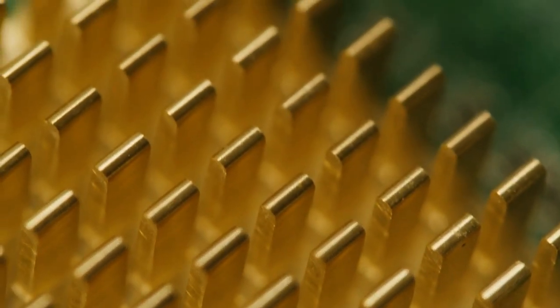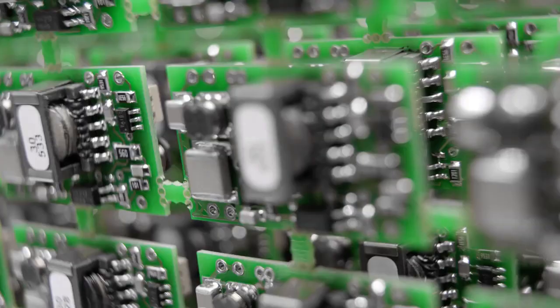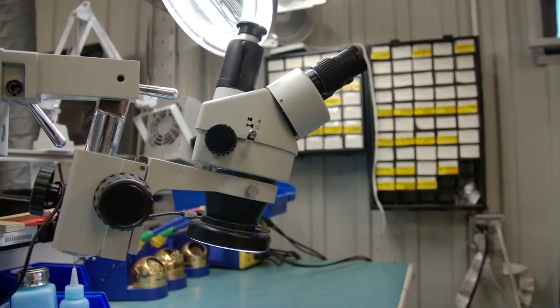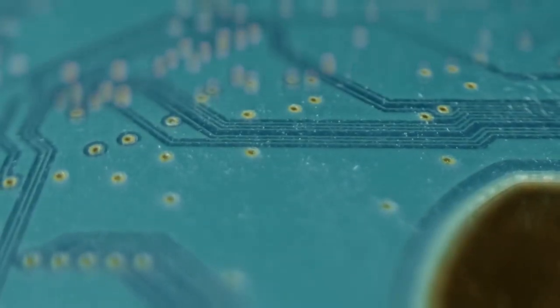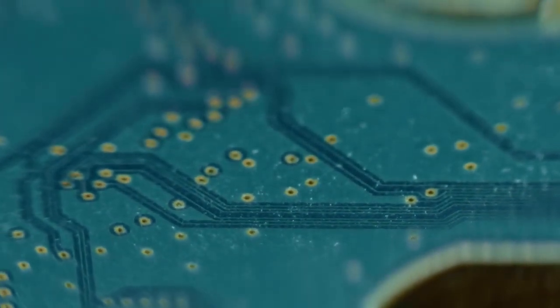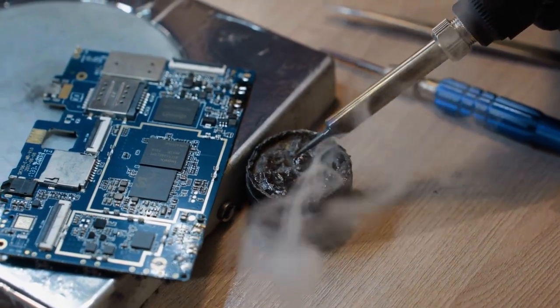When you press a simple push button, you expect a clean, instant on-off signal. However, the mechanical contacts inside the button don't make perfect contact immediately. Instead, they literally bounce against each other for a short period, typically a few milliseconds. This creates multiple rapid open and close transitions. A fast microcontroller or digital logic circuit can interpret these bounces as several presses, not just one. This leads to unexpected behavior and errors in your designs.